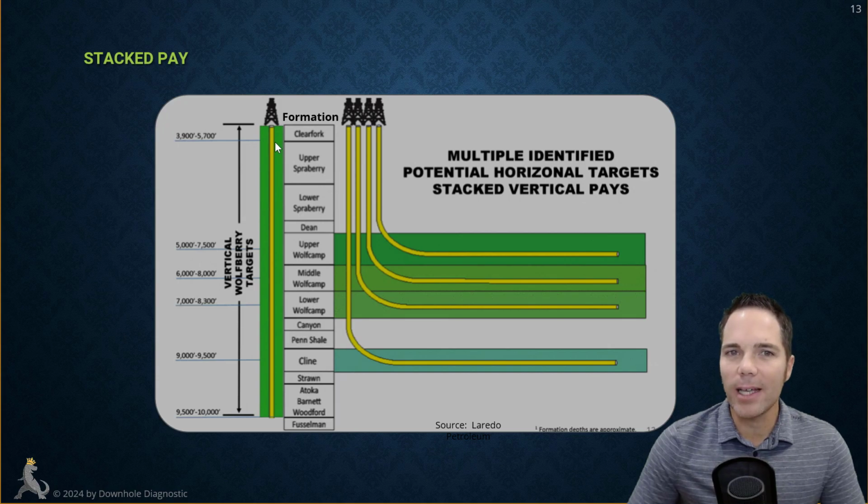And what's interesting about that is typically, or frequently I should say, we like to set the TAC above the top perforations so that we don't have solids stick to the TAC. If it's below the perforations, it's more likely to get stuck. But if you have one of these vertical wells with that huge completion, you might have 2,500 feet of unanchored tubing. Also, it's going to be more difficult to see a fluid level kick.